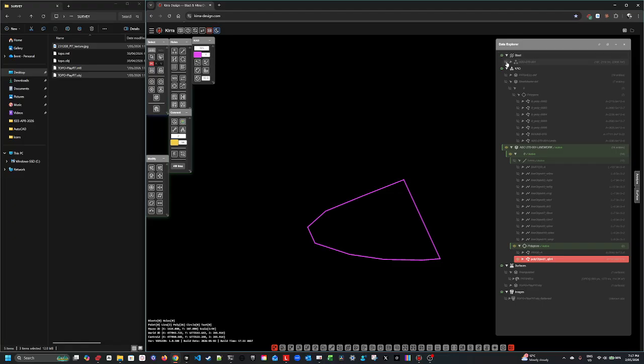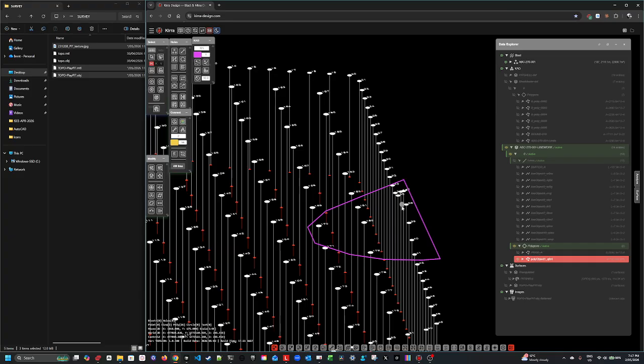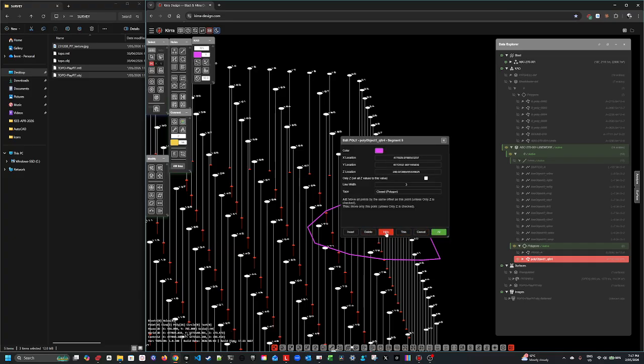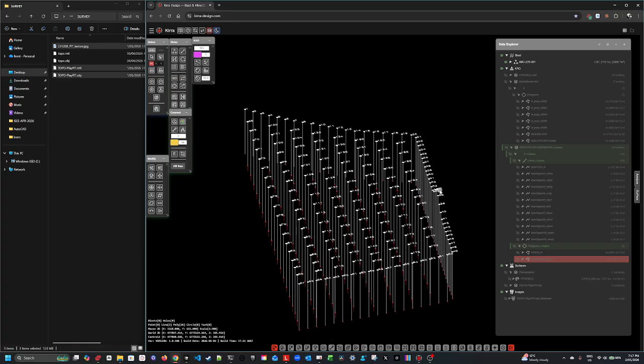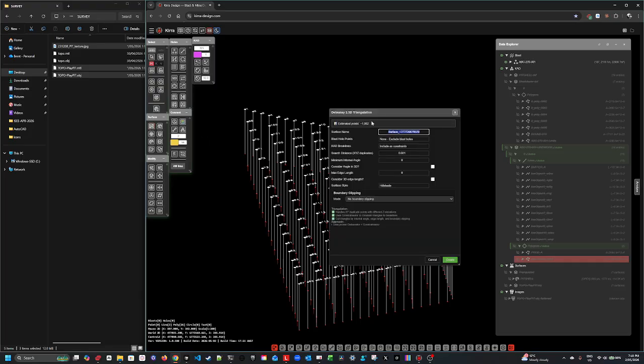We'll turn on our blast again. We can see our dodgy holes up here. We could just manually change those to lower, but let's triangulate these holes. So the first step is we want to hide everything that you don't want triangulated, hide it. Okay, so now we've just got the holes, and we're going to triangulate that. So we need the surface tool. There it is. We're going to triangulate that top button there, and we're going to call this topo.